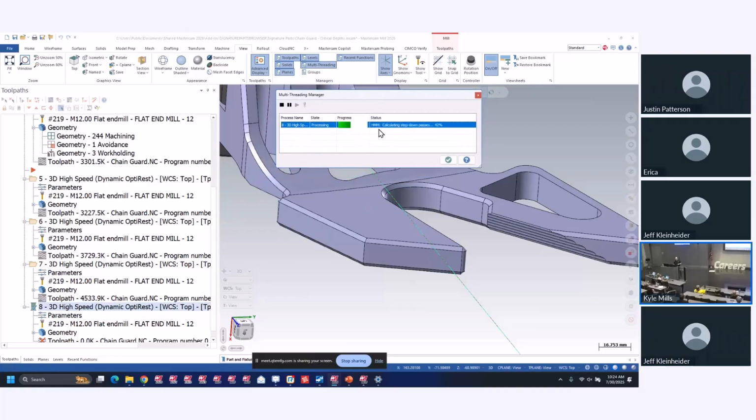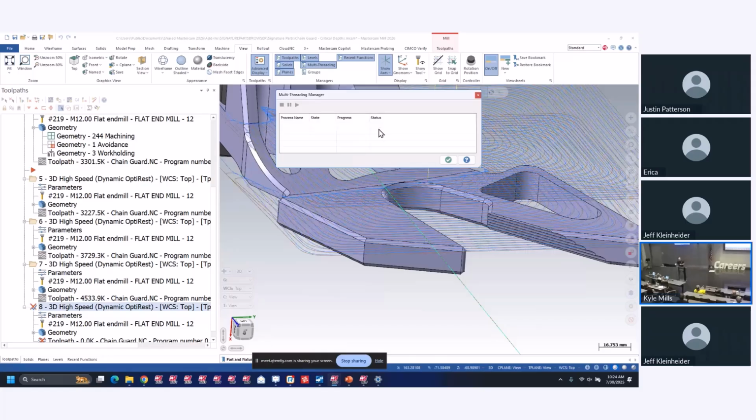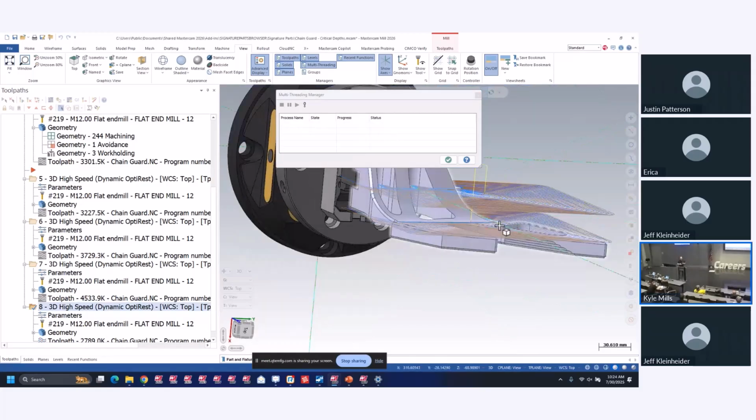Turn our feel good button on. Perfect. Now you see I have my two step downs, even though this doesn't really fall into that 400% of the tool diameter step down, it's going in and doing that flat that I picked.